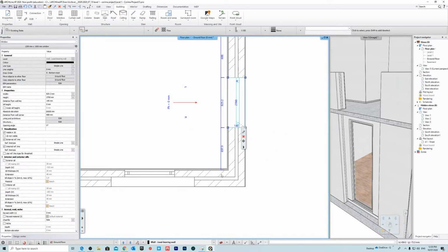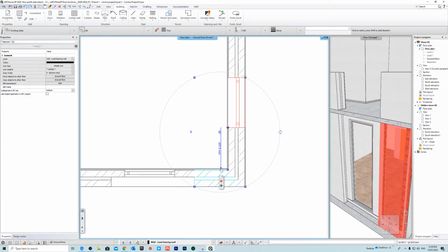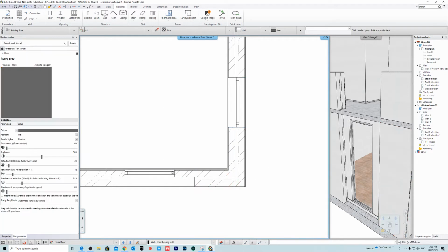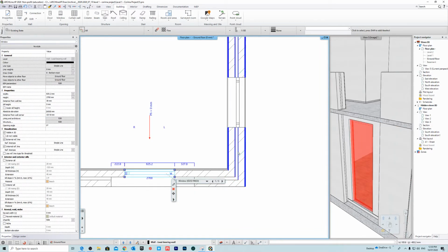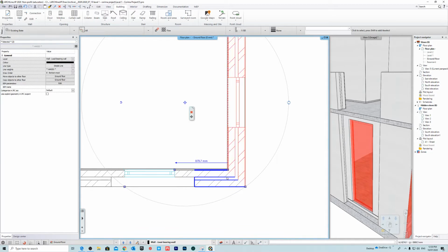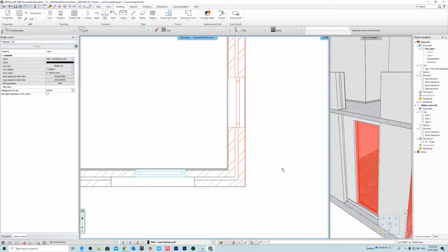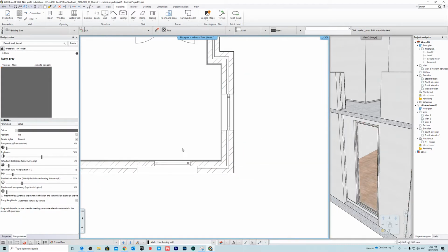Okay, so actually we need to hold shift, so click on this one, hold shift, change the direction like that, and we'll make this 700. Okay, so we can see that shifted across. Same for this one, so we'll click on this, hold shift like that, click on the arrow, switch directions, and we'll make this 700. Okay, so really easily we spaced that out equally.